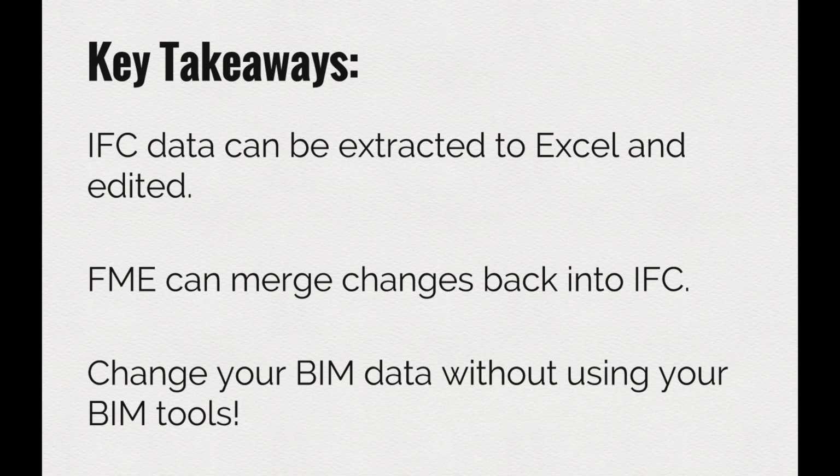And there's also things in FME that could tell you what you changed in Excel. Yeah. So if we had the original Excel and the new one, we can compare that as well if we really wanted to do that. So the other thing is you can change or update your BIM data without ever actually using BIM tools, because sometimes these batch changes are more efficient to be done non-interactively in this way.